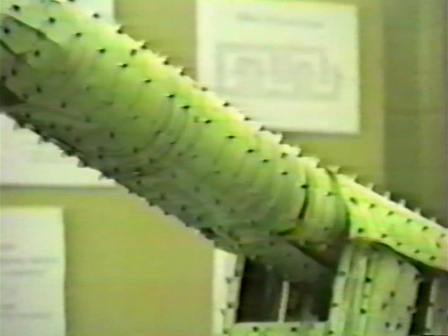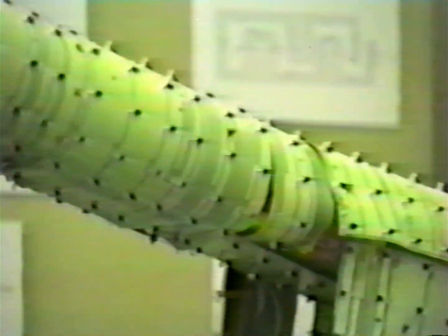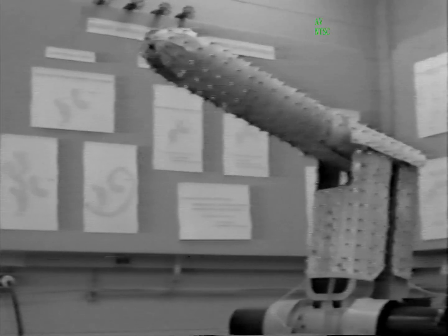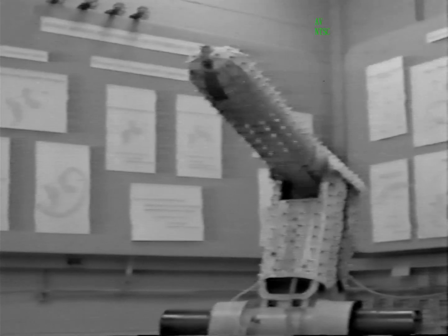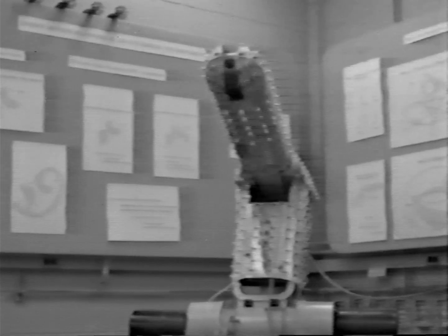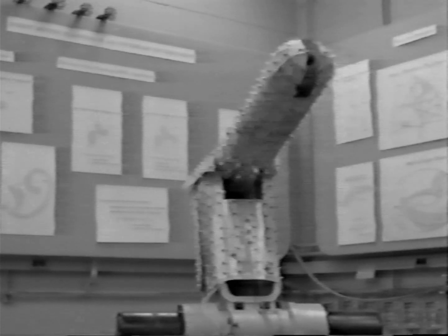Shown here are various views of the robot with the sensitive skin. There are no blind spots on the arm, thus an obstacle approaching from any direction will be detected. The intersensor spacing is less than 2 inches, depending on the curvature of the arm. Using a CCD camera that is sensitive to infrared light, you can see the pulsing of the LEDs. The scan rate is about 17 Hz. Thus, the entire skin is polled once every 17th of a second.